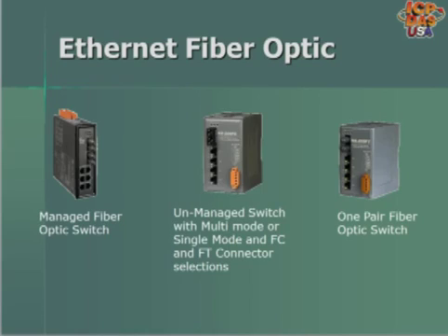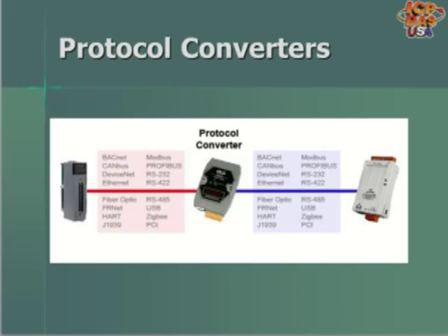We have multi-mode and single-mode fiber switch options which require different cables. Single mode has a small diameter core for light to go through it, and multi-mode has a large diameter core. Oftentimes, fiber cabling is already installed, so when adding a fiber switch to an application, you need to pick the fiber product that supports the same type of cable.